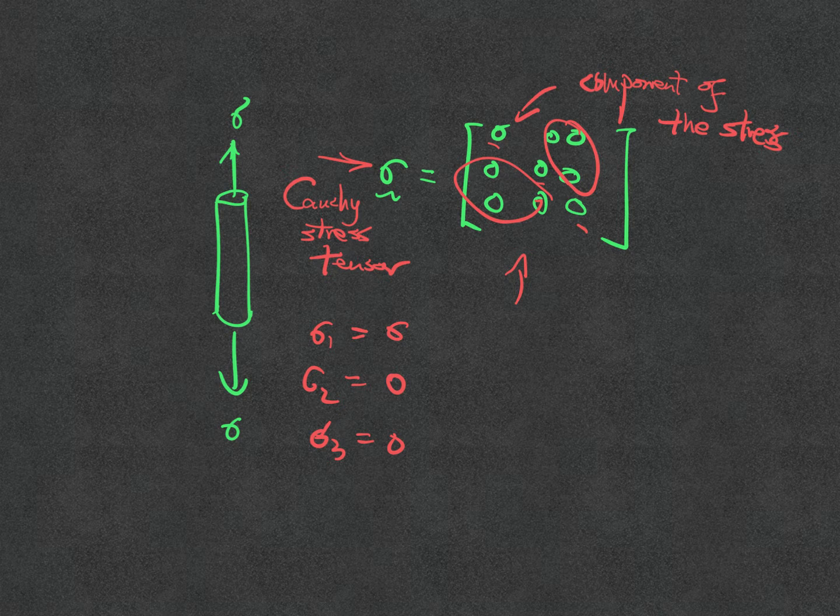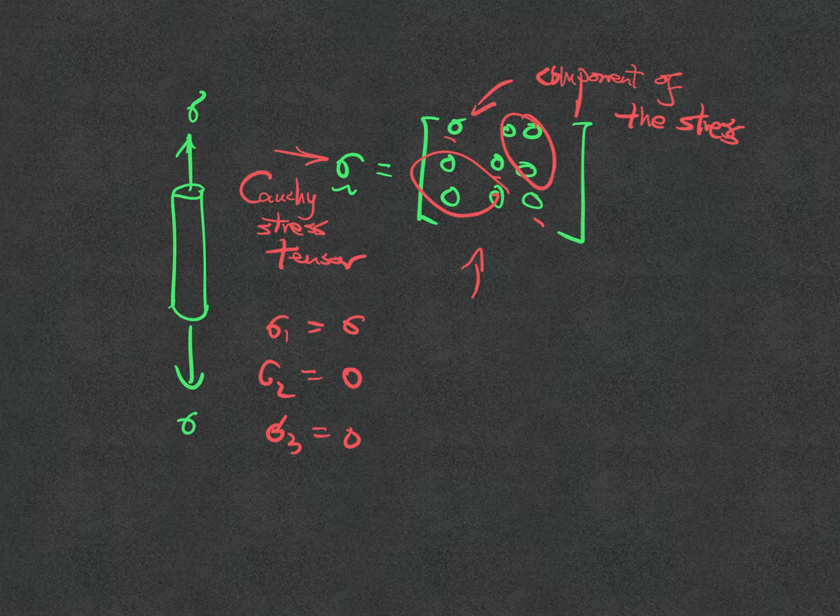tensor. Now, let me repeat what I'm saying and then try to compute the deviatoric stress. What is the deviatoric stress? The deviatoric stress is the total stress minus the volumetric part. P is a normal stress applied evenly everywhere on the surface, like a balloon. If a circular balloon becomes smaller, it is subject to isotropic stress, and isotropic stress can be expressed as a scalar times the identity matrix.